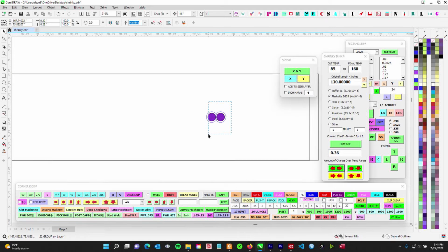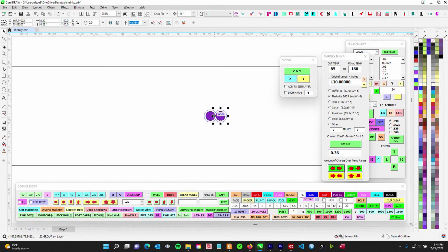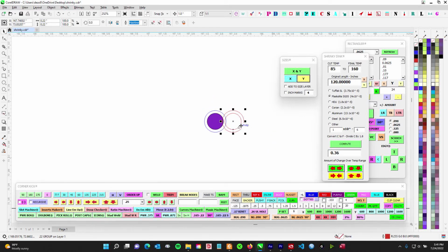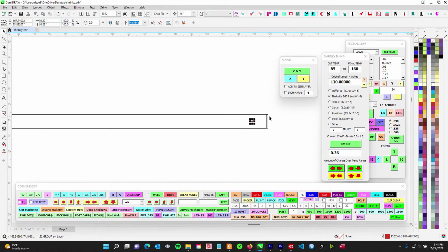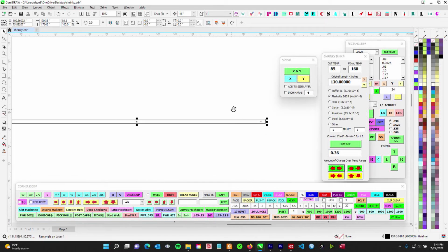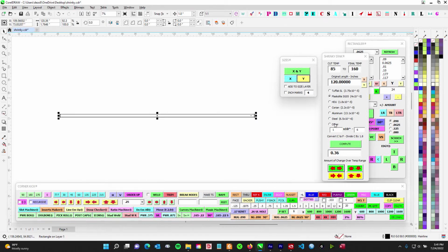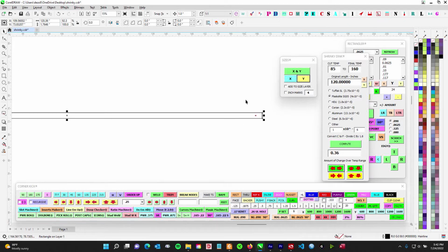I know this is fairly simple. It doesn't move exactly linear, but you can see how much this stud wanted to move. It's almost an entire stud over. So what had happened was the bar grew in the sun and it just sheared its own studs off and it popped right off. So again, knowing this information saves us.